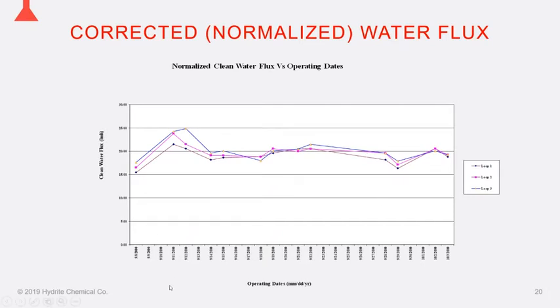You will have some normal day-to-day fluctuation, but for the most part, you should establish an upper and lower control limit average that the system should return to. And then you can see somewhere towards the end of this graph where we took a dip, and then it slowly recovered, that could have been an upset during the day. We could have had a pasteurizer divert.